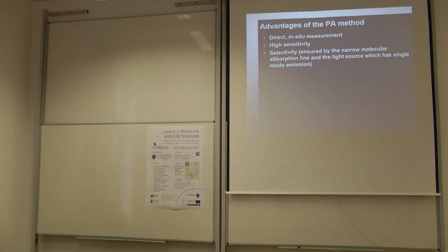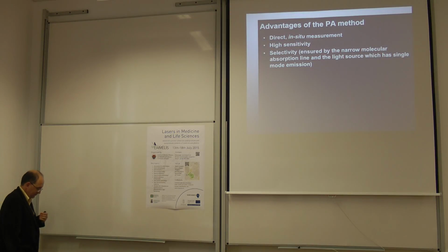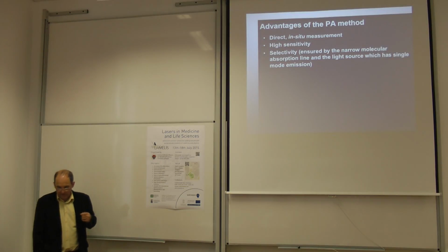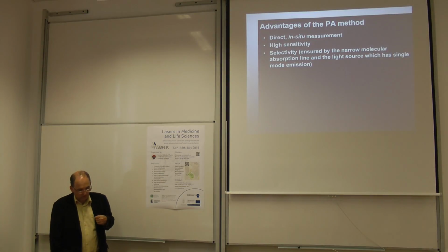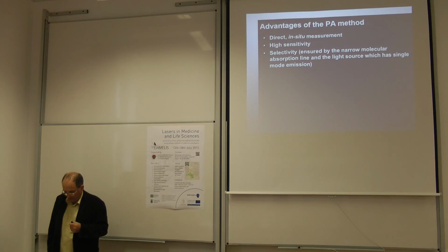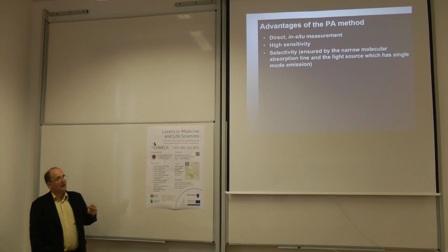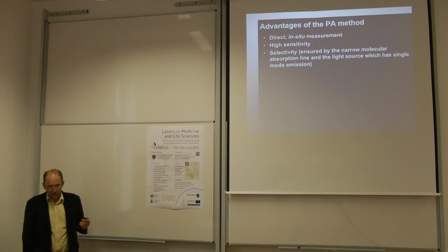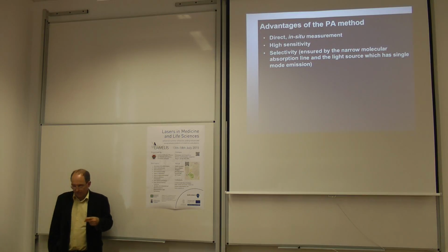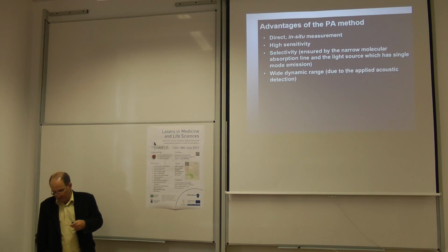There is also good selectivity, which means that if you have a proper light source and you are operating it at a proper wavelength, you can ensure that only the component which you want to measure generates the acoustic signal. So in a complicated gas mixture, you can make a selective measurement of the targeted molecule.